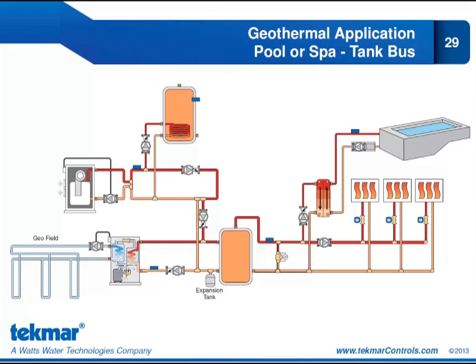Now, one thing you have to be mindful of in this case is that these zones could not be heat-cool zones if you wanted to have year-round pool or spa heating. So we are limited in that regard. We could not do radiant floor cooling if we wanted to have year-round heating of a pool or spa. So in this case, there would be no switchover of my tank. My tank would be for heat only year-round.